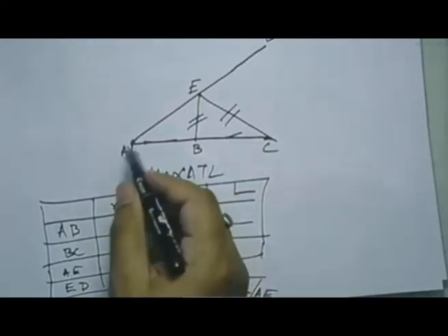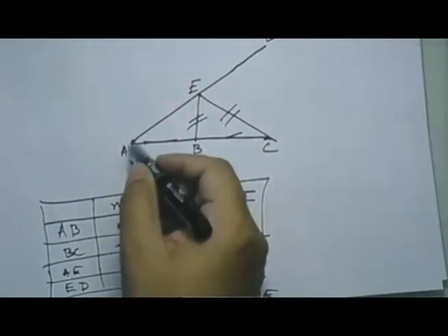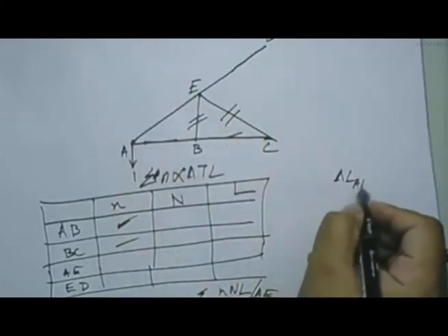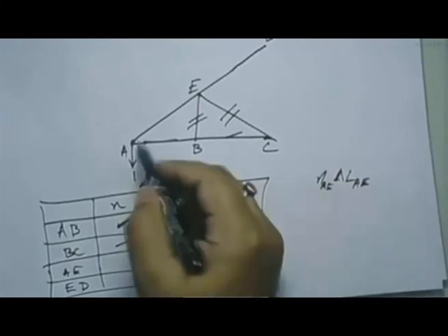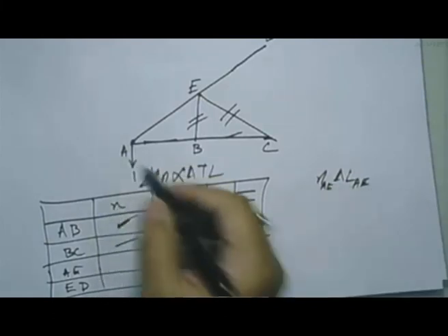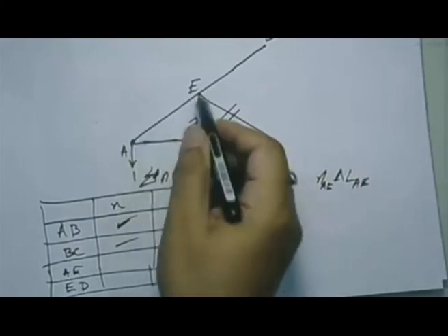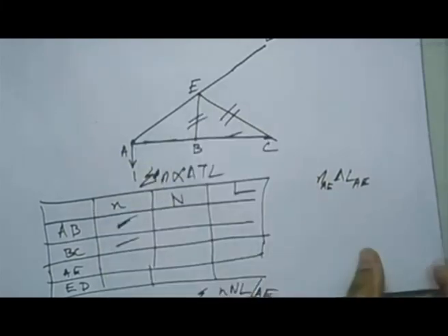For calculating deflection of this joint due to the fabrication error here, the fabrication error is delta L in AE. Just multiply it with N of AE. That is the member force in this member due to this virtual load. So that will straight away give you the vertical deflection of this joint due to the fabrication error in this member AE.